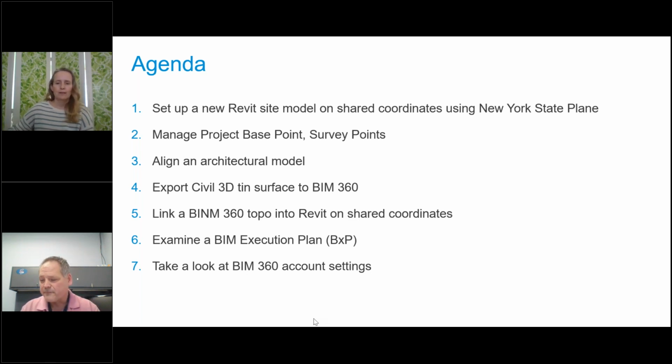The most important part, obviously, is to get our Revit model geolocated. With Revit 2019 and up, they've had some advancements in terms of pulling in state plane information into Revit to really be able to verify that you're in the right spot. Once we're able to pull that information in, it's a little less stressful. To be honest, this is probably the most stressful part of my job, making sure models are lined up and coordinated. Then we'll just go through the clicks of Revit to get the stuff in.